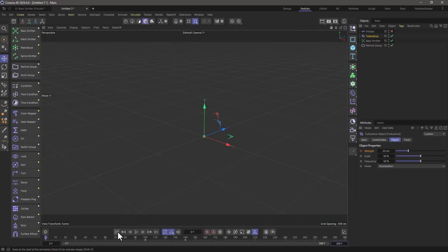So now I'm going to go to the same keyframes at frame 100. I'm going to activate my friction, and I'm going to set it to 0 at frame 100. And at frame 140, right here, I'm going to set my friction to 50. And these are just numbers I found by playing around. You will art direct it in this way. Again, I'm going to set this to 200. I just wanted to show you that they go in a straight line.